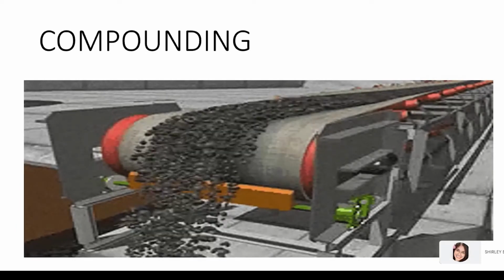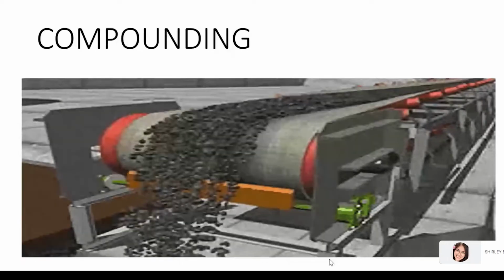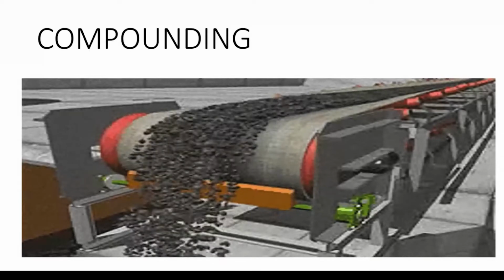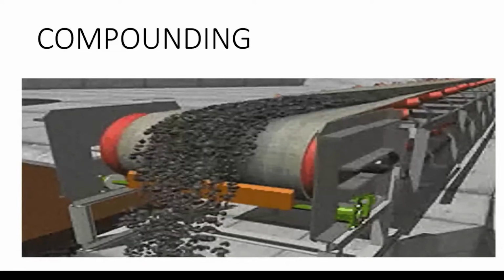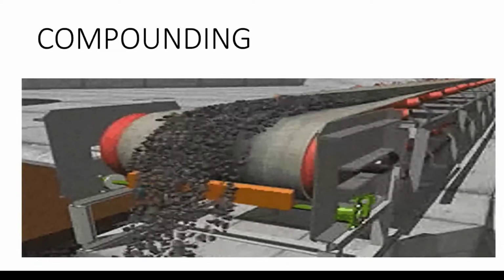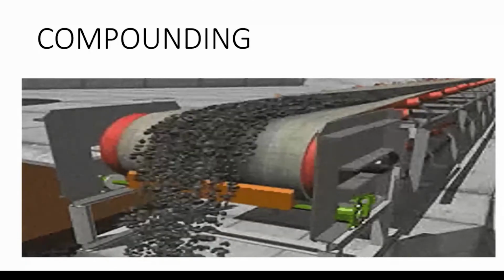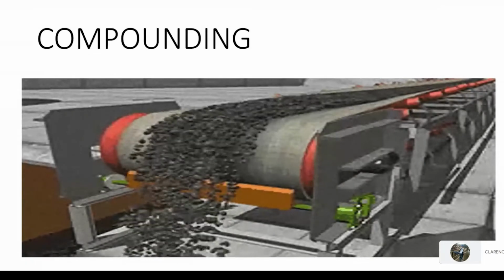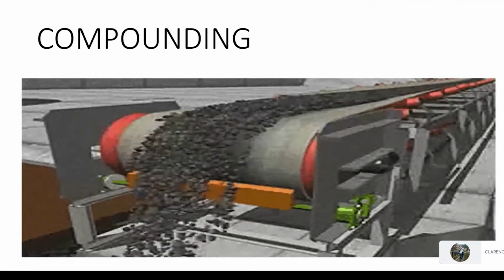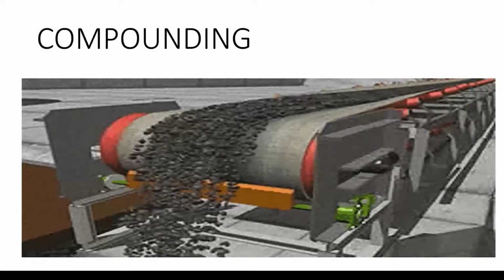Natural rubber changes with temperature, becoming brittle with cold and sticky with heat. Chemicals added during compounding react with the rubber during the vulcanizing process to stabilize the rubber polymers. Additional additives may include reinforcing fillers to enhance the properties of the rubber or non-reinforcing fillers to extend the rubber, which reduces the cost.